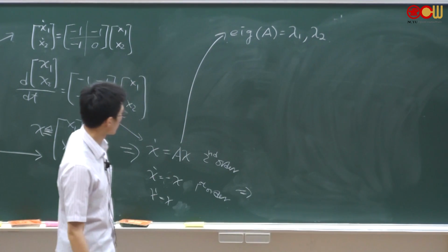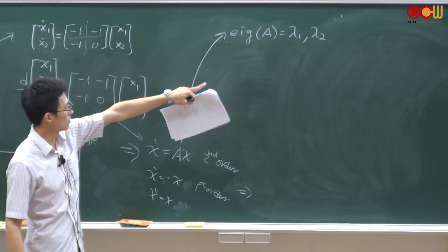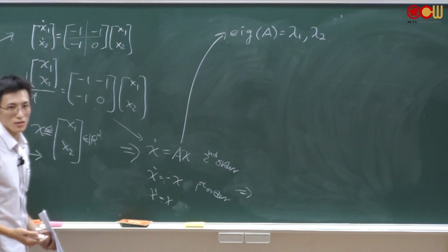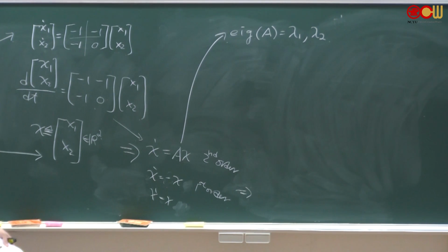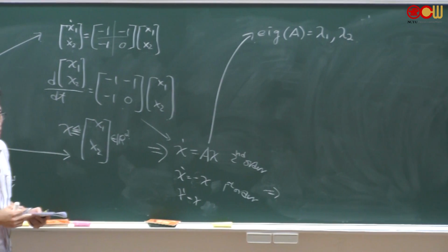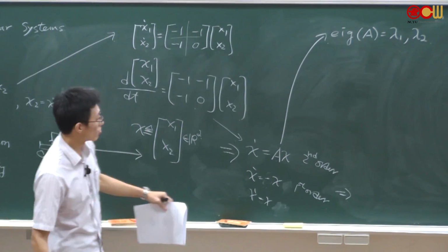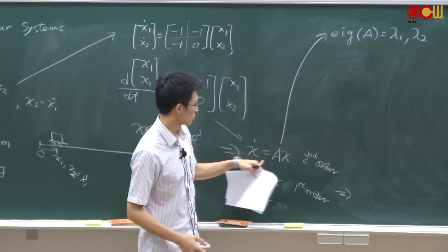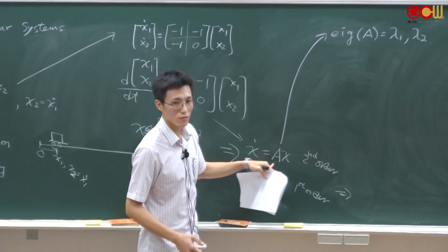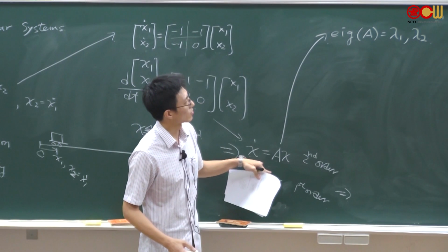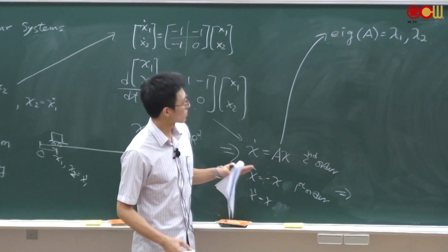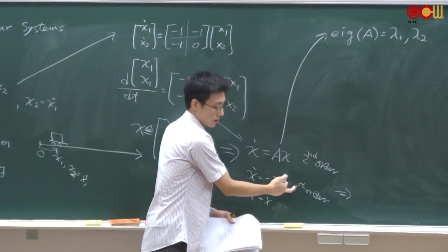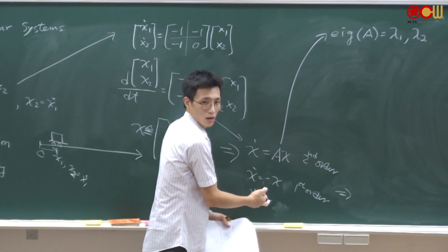Because A is a 2x2 matrix, you will obtain 2 eigenvalues. Both eigenvalues are negative, the system is stable. If any one of the eigenvalues is positive, it is unstable. You can still solve for x in this 2-dimensional second order system, right? You can solve it and evaluate if that's correct or not. But basically, it's an analogy comparing the second and first order systems, okay?